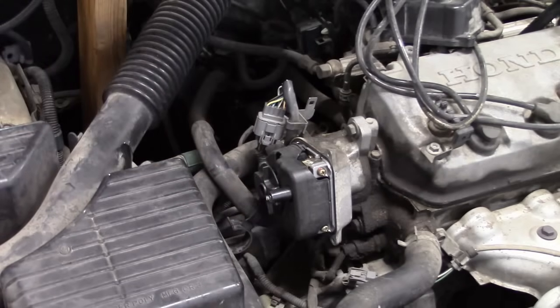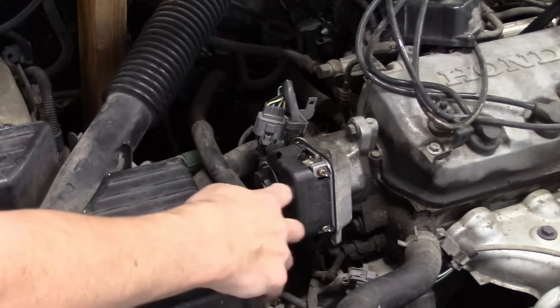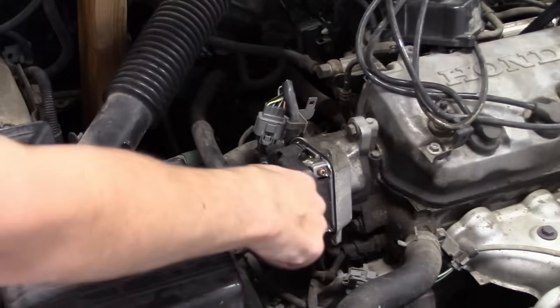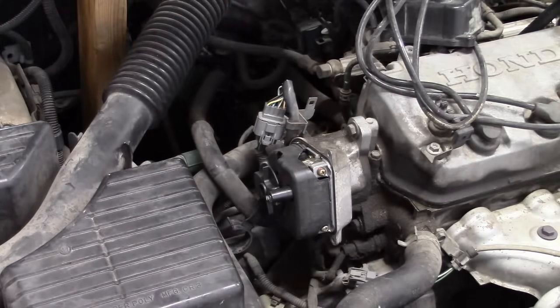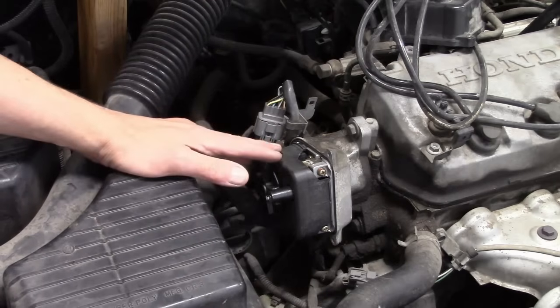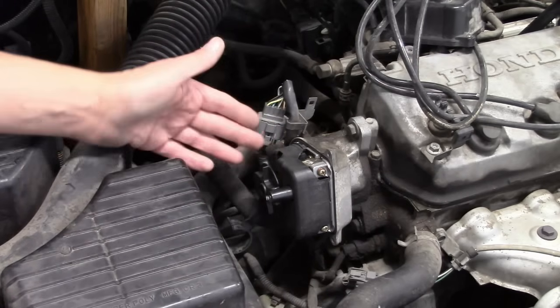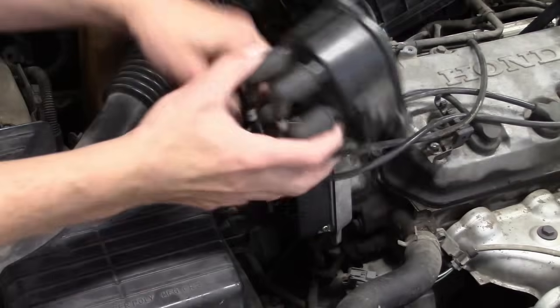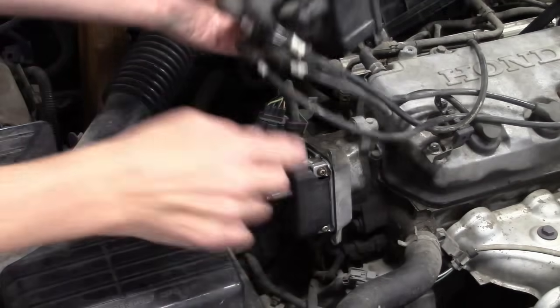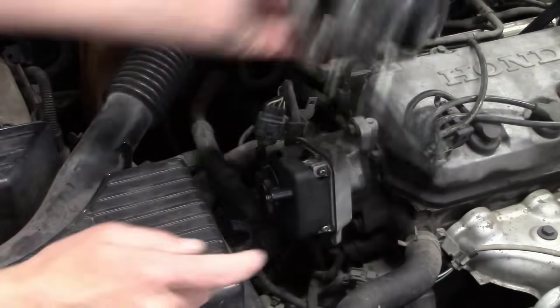The other thing as well was that this is the main spark output. Usually you're used to there being a wire that comes out of here and goes to the distributor cap. So you'll have 9 wires on a V8 or 5 wires on a 4-cylinder, that kind of thing. This cap only has 4 wires because the main output is internal in the cap.